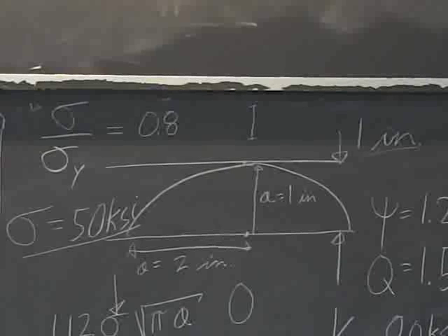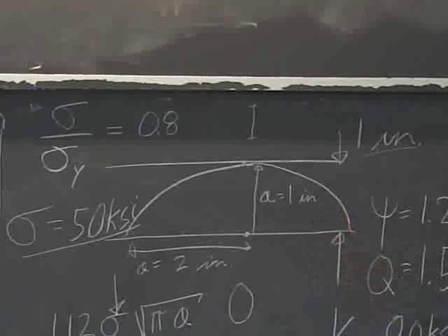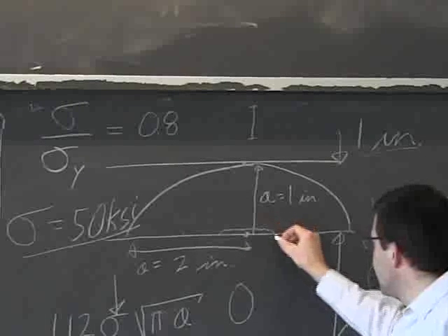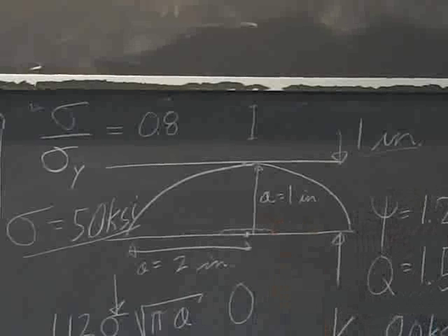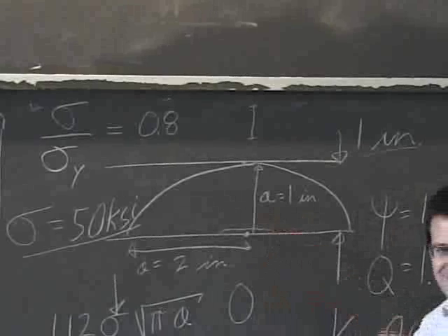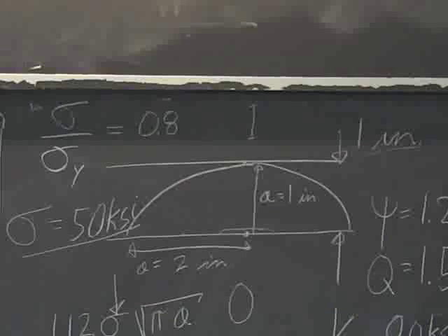We didn't talk about this, but this crack can come up just by stress cracking, which we mentioned. That would be just growing slowly under a steady load because of the environment. Or it could be cyclic load because of pressure variations. It could start from an initial flaw. Maybe you had an imperfection here that created it in the first place. Maybe it starts from the toe of the weld. That's actually likely. But at the end of the day, it's the same idea.